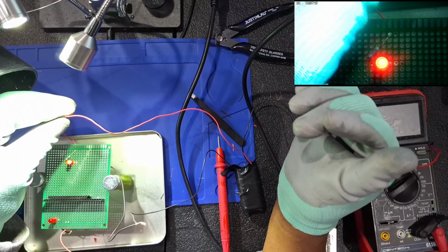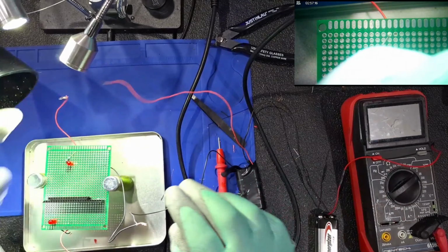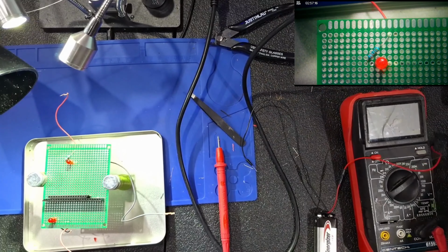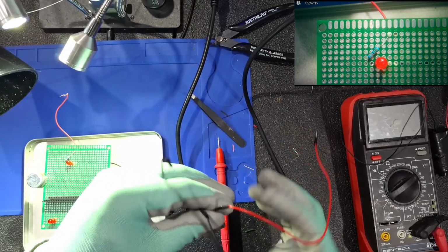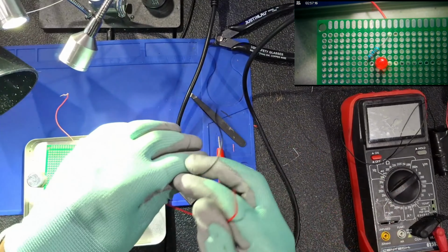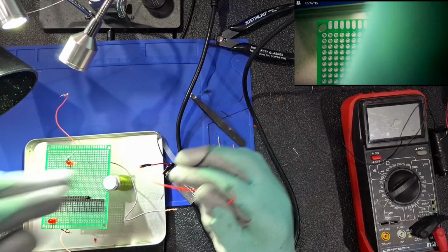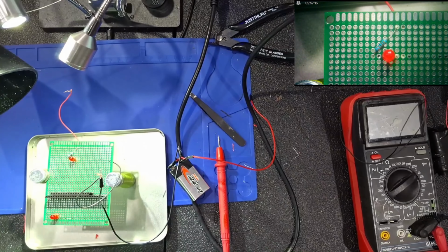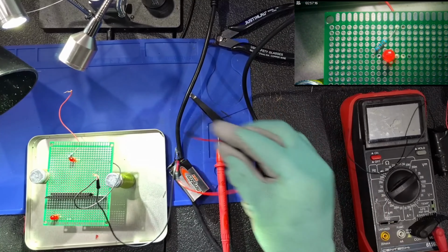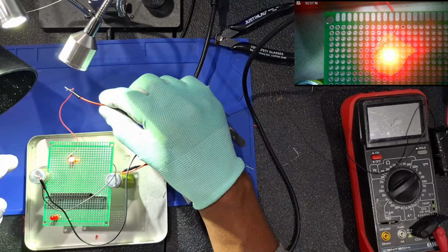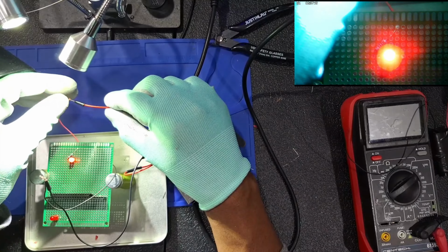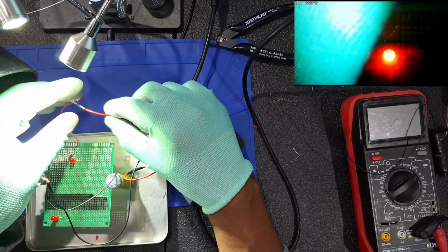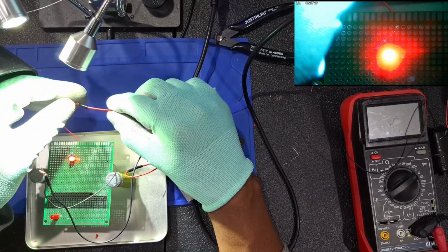I also have a resistor between the battery and the LED to prevent the LED from burning up, because in previous lessons I learned that I need only 2 volts from a 9-volt battery to light up this LED. So as you can see here, every time I connect the positive wire together, it completes the circuit. Electrons flow, the charge lights up the LED. Once I remove it, no light, it breaks the circuit. So it's as simple as that pretty much.